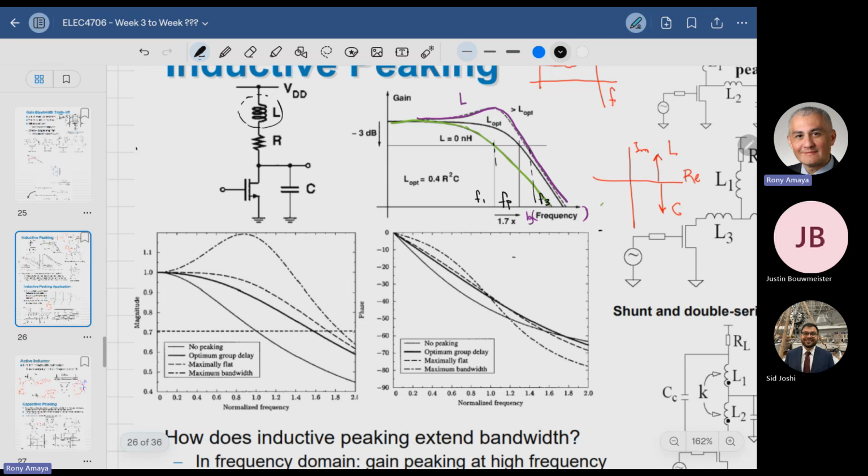Based on what you know now, based on the first few lectures: we want gain, but especially with a broadband signal, remember, you have a very large spectrum of data that you're trying to pass. You're not evenly amplifying your signal passband anymore. So different parts of the spectrum get a different gain, and obviously a different phase, which you have in the plotting here. As a result of those two, you're also going to have group delay variations, and those group delay variations are going to come back and close the eye.